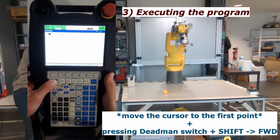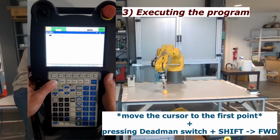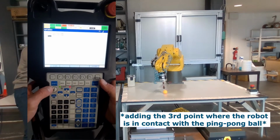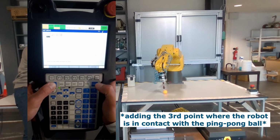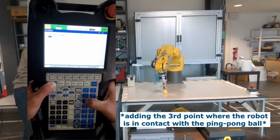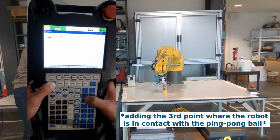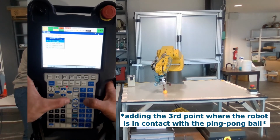As we can see, so far so good. The robot is moving between the two defined points. Now I will create a third point where the gripper will be in contact with the ball. It is mandatory for this type of gripper to be in contact with the object before we can order the robot to pick it up.